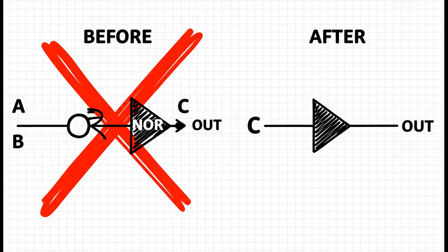So the consequence for the whole circuit is pretty significant. The intended function was to NOR input C with the output of the A plus B OR gate. But now, with that first gate stuck at a constant logic 0, the A and B inputs do absolutely nothing. They're totally irrelevant. The entire circuit's function just collapses to simply inverting input C. And this is a huge lesson. A single, simple component failure can silently and fundamentally change a circuit's entire behavior.